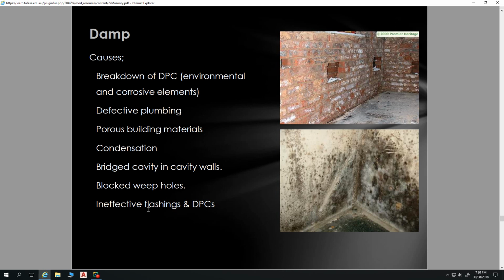But yeah, these old bricks, they're not as thoroughly fired as the new bricks, and they're also far more susceptible to moisture and deposited salts. The moisture gets into the brick and then comes out as salt, and deposits salt on the outside. Those salts form crystals. They wedge off tiny little bits of brick and very slowly eat away at the brick or the masonry wall.